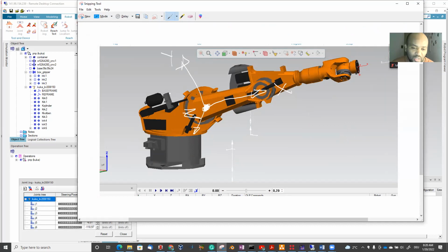Now the same is true here. It is the axis of rotation. We assign z here. We assign x along the link. Then we assign the y-axis along this, maybe. The same is true for this: we assign the z-axis along the axis of rotation. Then we assign the x-axis along the link axis. And the third one depends on the right-hand rule, I believe.